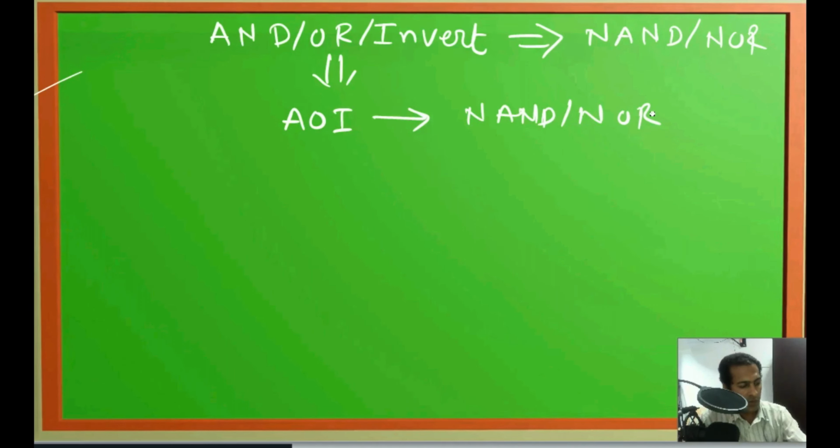In the designing of digital circuits, the minimal Boolean expressions are usually obtained in SOP form or POS form. Sometimes the minimal expression may also be expressed in hybrid form. The SOP form is implemented using a group of AND gates whose outputs are ORed, and product of sum forms are implemented using a group of OR gates whose outputs are given to AND.